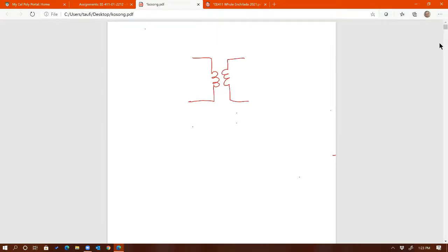So if you have a transformer, an isolated topology basically, a topology that uses a transformer, then this transformer has, as you learned, magnetizing inductance, core loss, right? And then it has the copper loss and leakage inductance.